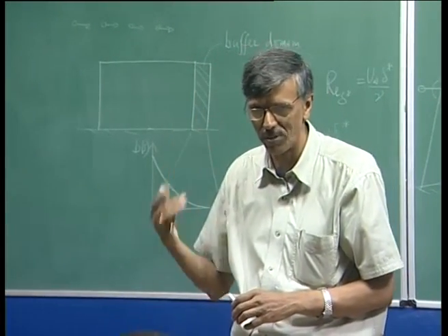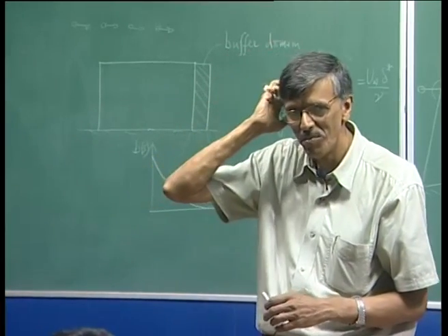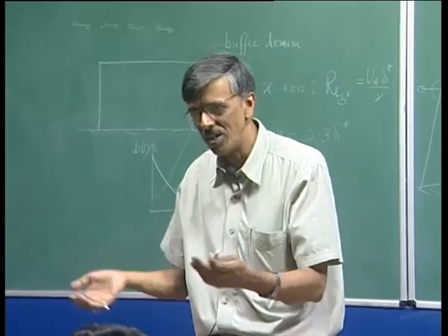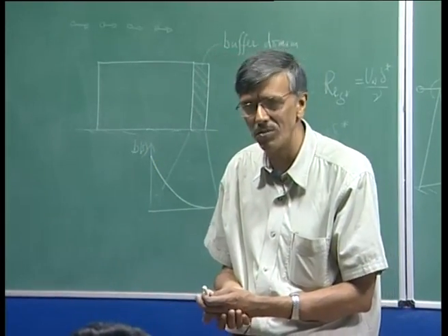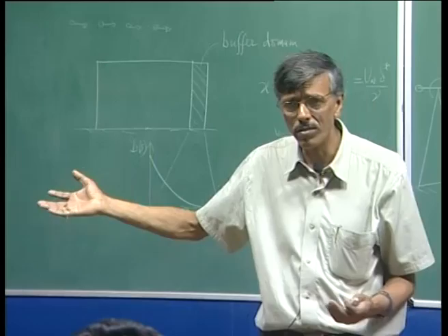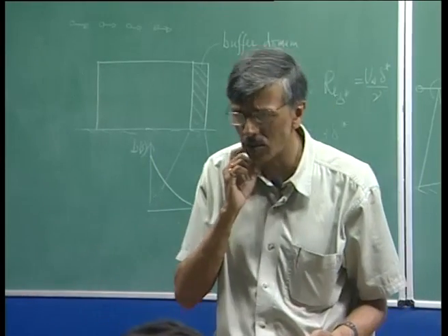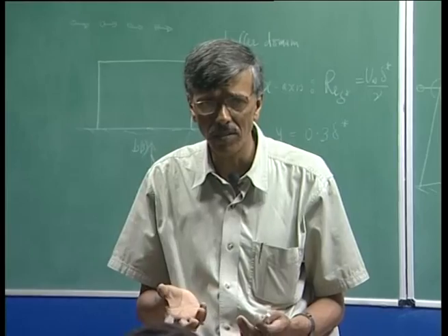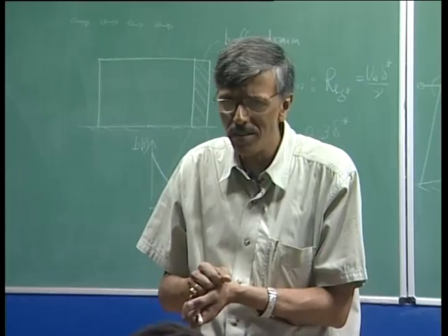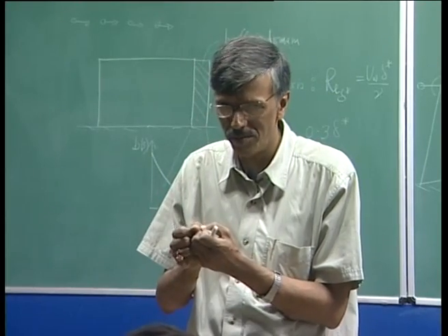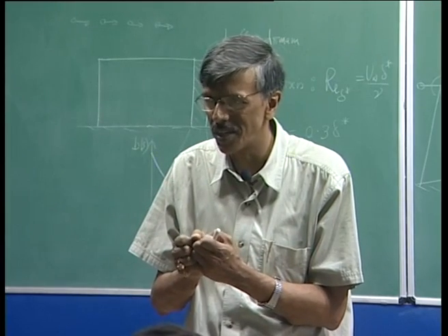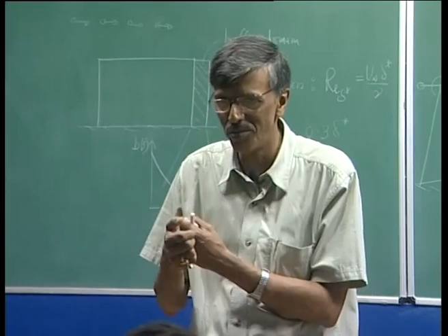That was the reason we proposed this model, and we wanted to show the receptivity of the shear layer to periodically convecting vortices. You would see an identical scenario, and it is quite relevant if you are looking at an internal flow inside a turbo machine: the vortices will be shed from the rotor. They will be essentially viscous vortices. They will not go at c equal to u infinity.